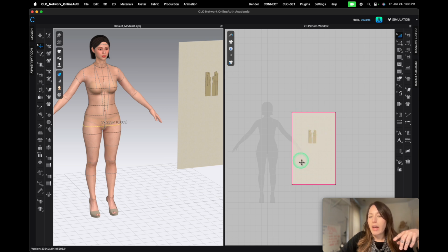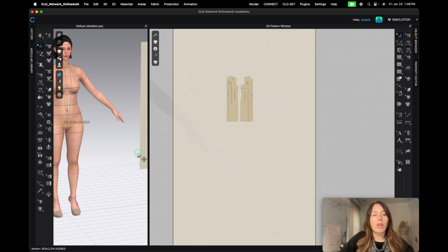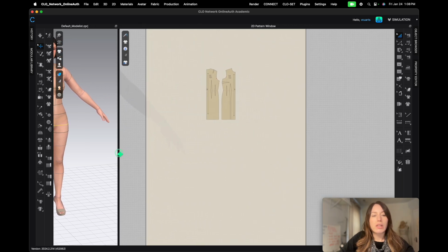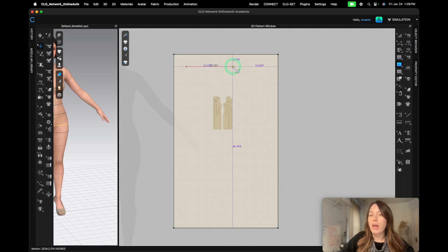So we have to have some device that we can scale it to. We can do this a few ways. I can put a line in there using my internal line tool, just using this tool right here, right under your polygon tool. Remember, these are internal lines, actionable lines. You know they're internal lines when they are red here.